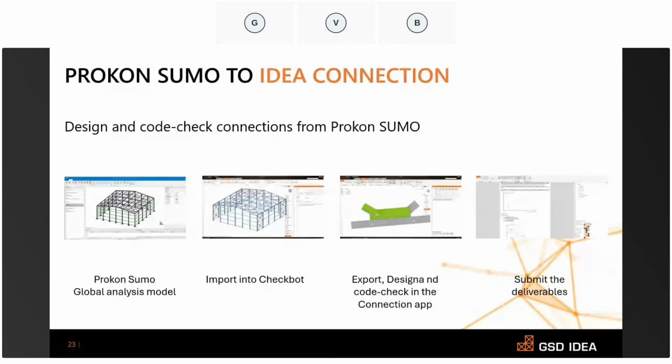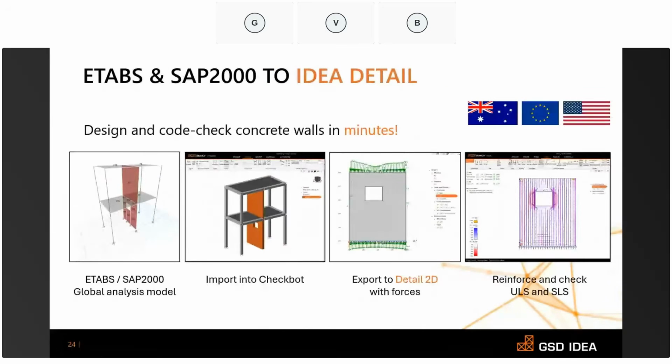And now the next link is a completely new workflow designed especially for those working with concrete walls. And the link is from ETABS and SAP 2000 to IDEA StatiCa Detail 2D. Until now, checking wall behavior was done directly in ETABS or SAP 2000. It was limited, mainly because those are linear analyses, and effects like the compression softening of concrete weren't captured accurately.